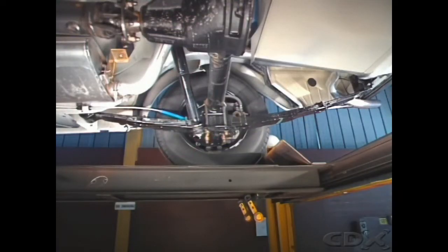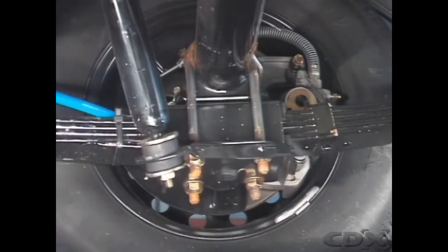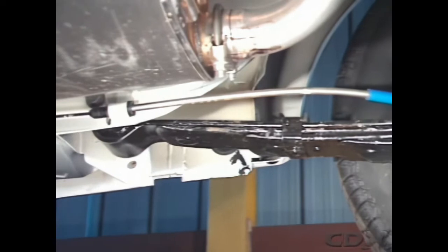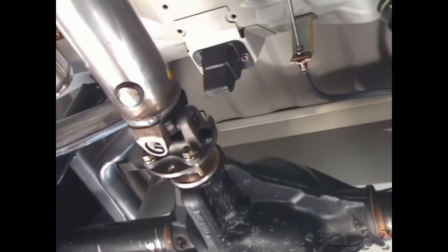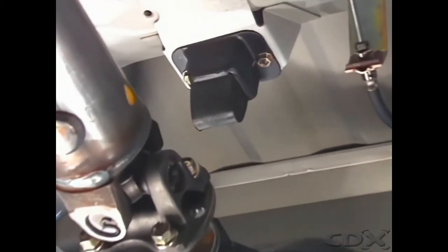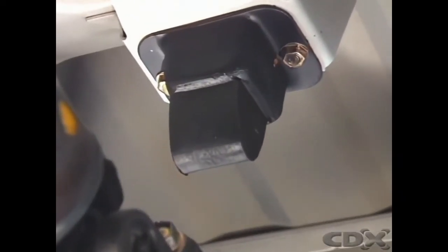It's usually controlled by mounting the axle housing closer to the fixed shackle point, so that the spring's front section is shorter than the rear section. The short, stiff front section resists twisting, and a bump stop above the final drive housing can also be used to restrict upward motion during acceleration.